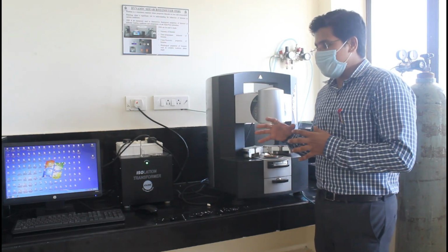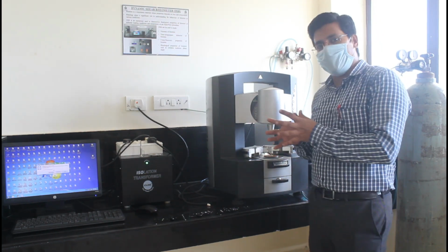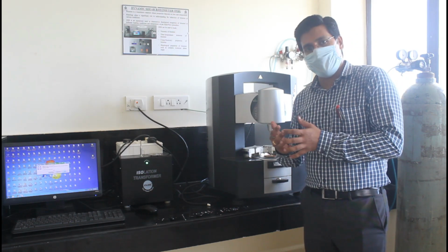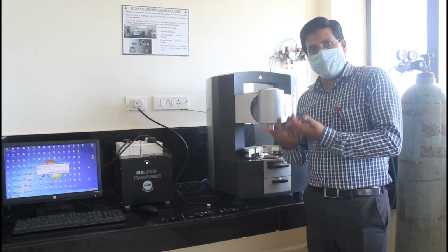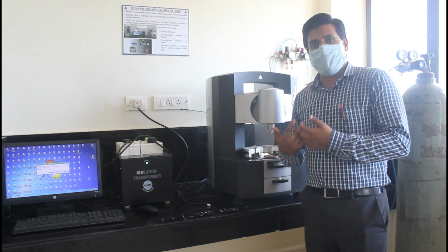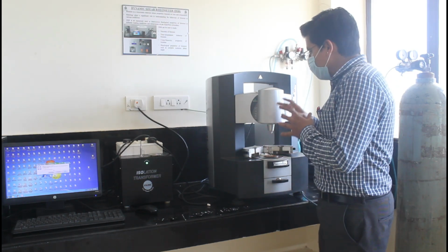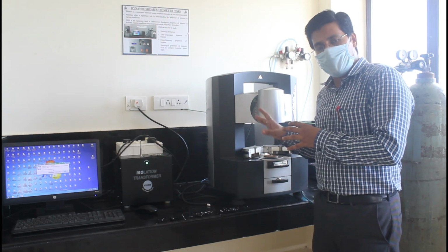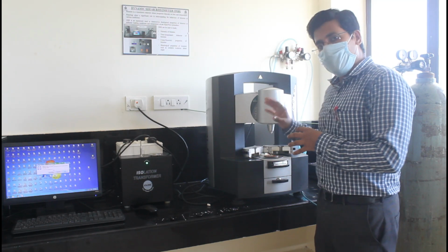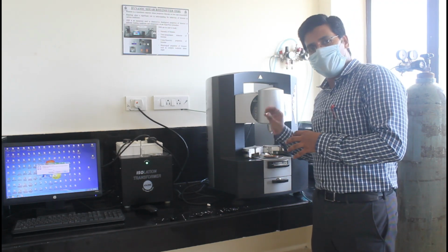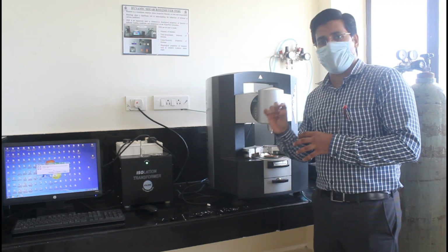studies. These kinds of properties will indicate the bitumen properties in the short term and in the long term also. How it will behave over time for different frequencies, different temperatures. This dynamic shear rheometer can simulate all these conditions. But it is only the bitumen, not the mix. So in this study only the bitumen properties are measured, not the mixture properties, right?